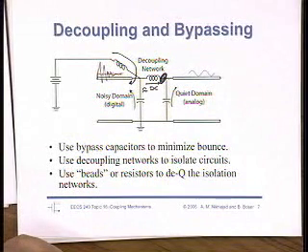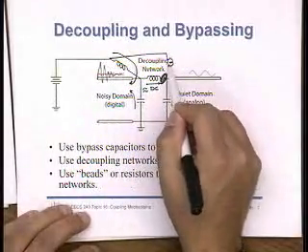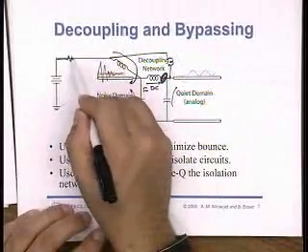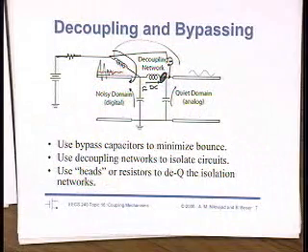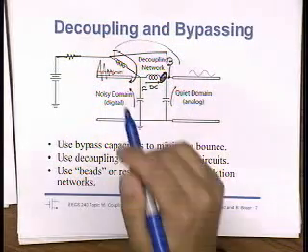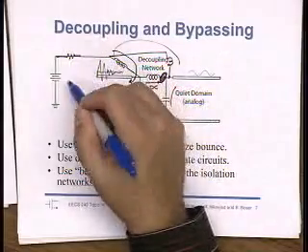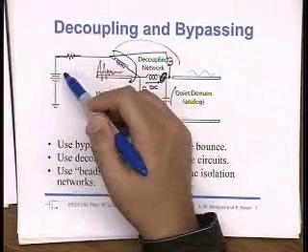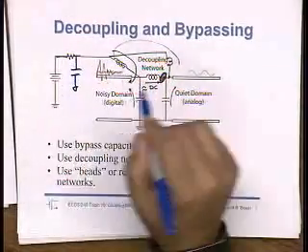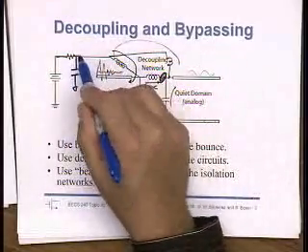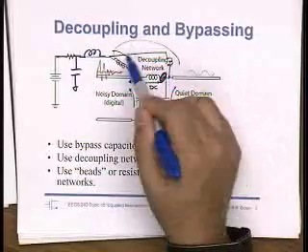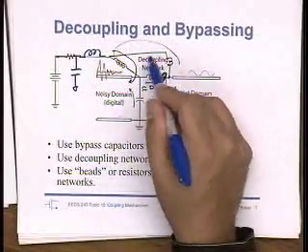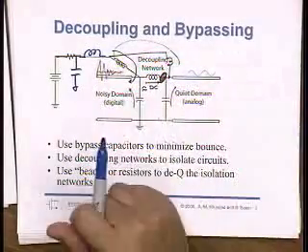How about connecting the other side, instead of to digital VCC, to the supply source, and making the two inductors run parallel with each other? Yeah, you could do it that way as well. But because the supply has finite impedance at high frequency, there's still a path coming back. That's a very good question. Of course, that's a smarter thing to do. But as we talked about last lecture, at high frequencies, a regulator or even a battery would have finite impedance, so we would try to decouple it for one thing. And this is also going to be far away, so this inductance is going to be pretty high. So this network is still going to be there, but instead of putting down a physical inductor, you may end up just being able to use the leads, the traces, as your inductance. That's a great point. Thanks.